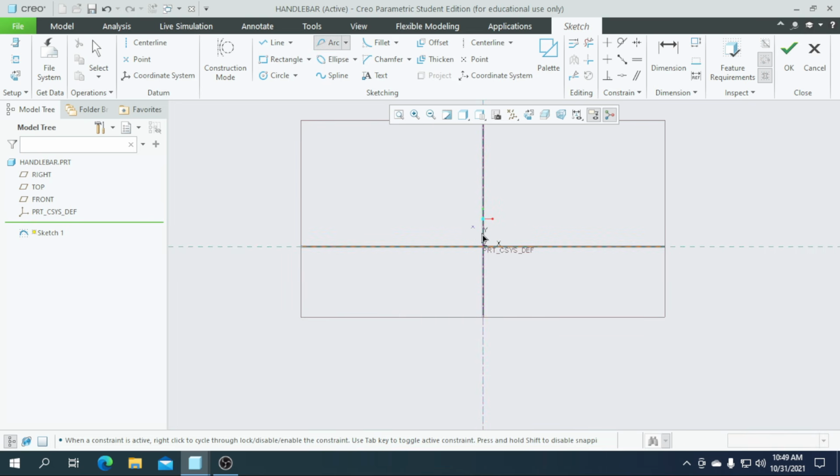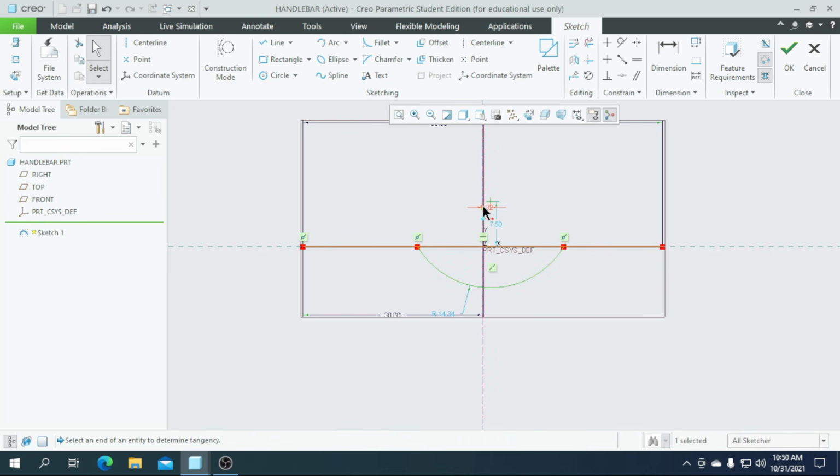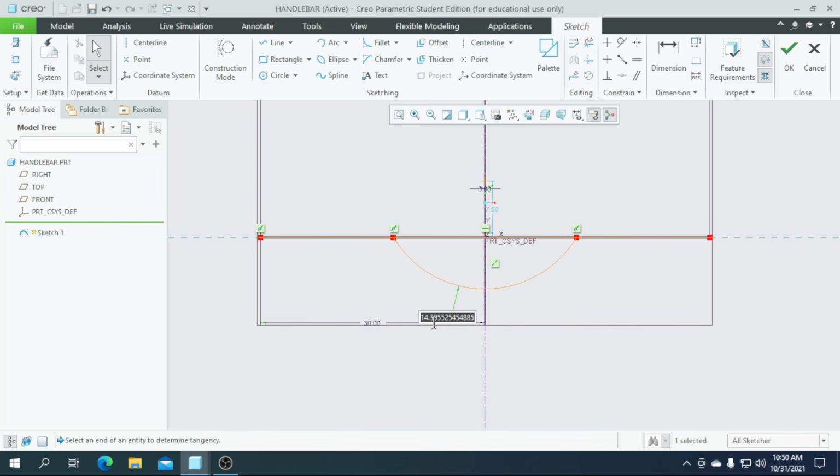So now I am going to create an arc here, or else you can draw a circle. Yeah, for this conic arc is best, or else you can draw a normal arc. And enter this value as to be 0, enter a radius of 13 or 12. 11 is okay for us, enter a value of 12.